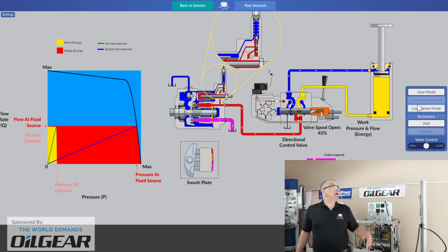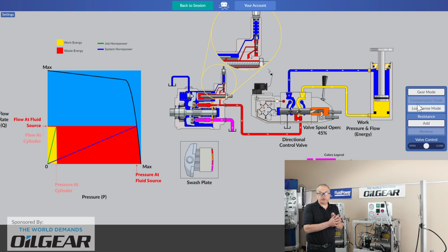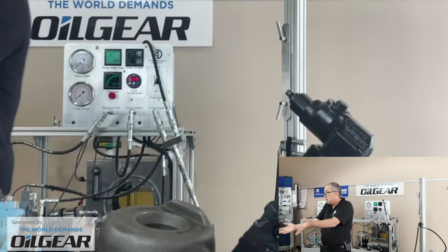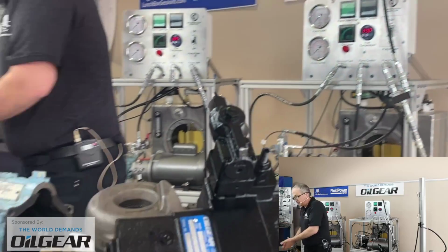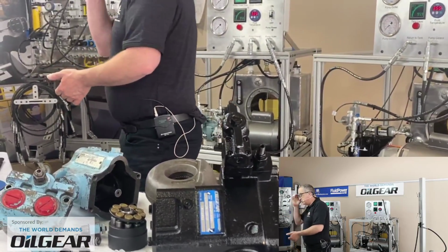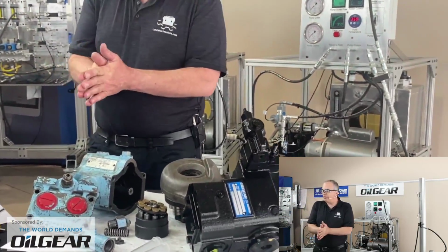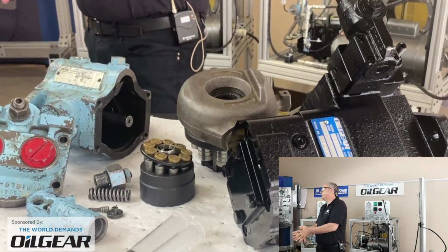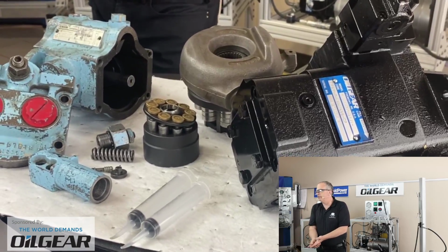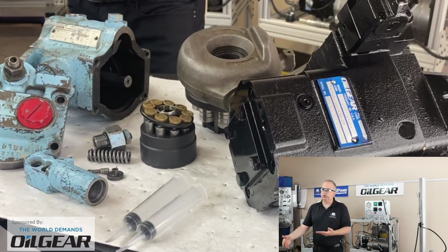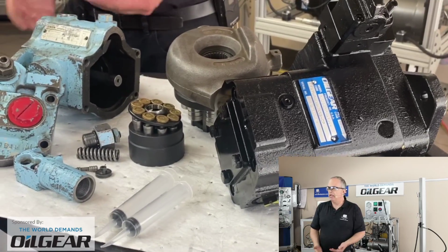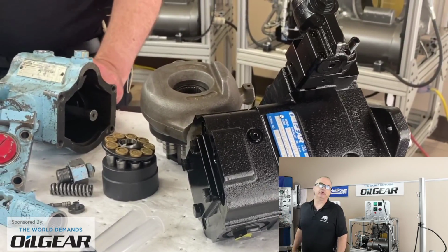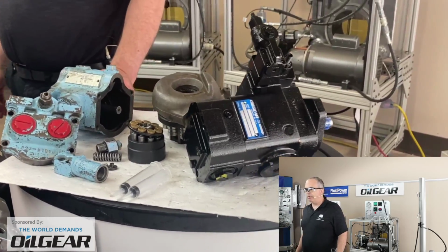All right, so to answer our pop quiz question of the day, which I think was, why use one of these swash plate pumps? I think that you can see, and I see that some of you have certainly answered it there. You've got it right. This type of pump will save you some energy, for certain. Energy at the electric level if it's an industrial plant, or diesel fuel if you're working with an engine-powered prime mover perhaps. And if you save that energy, then you also keep your hydraulic system a bit cooler.